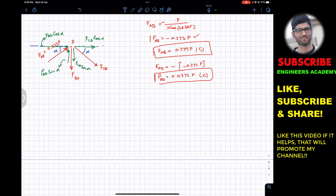Now considering this joint D, if we apply the summation of forces along x, that must be equal to 0. Towards the right is our positive x direction. So we have this FCD cos of alpha, so plus FCD cos of alpha, and then we have FAD cos of alpha, so plus FAD cos of alpha. This is equal to 0. And if we divide the whole equation by cos of alpha, we will get FCD plus FAD equals to 0. And from this we can say that FCD is equal to minus FAD.